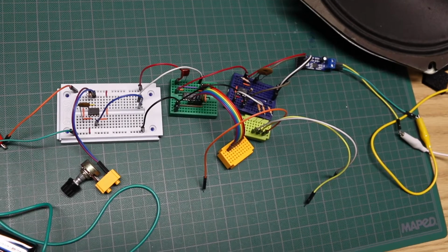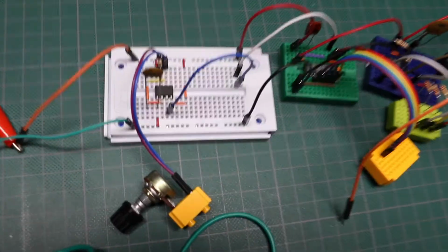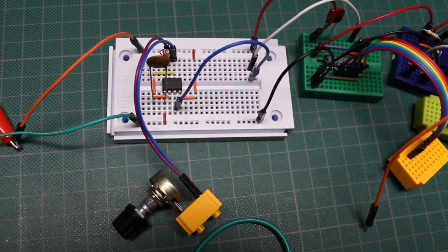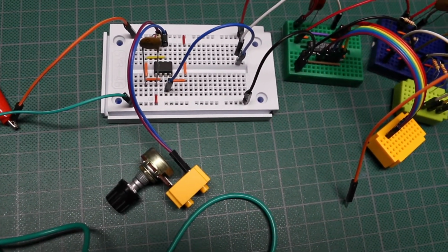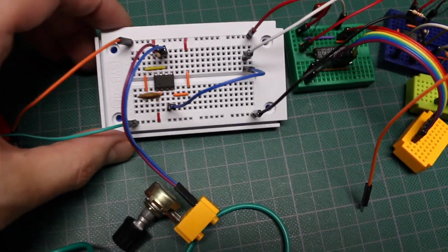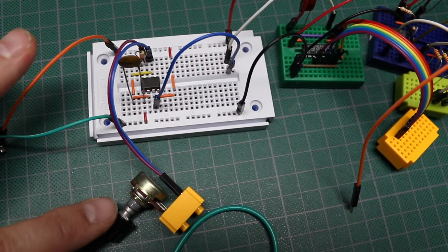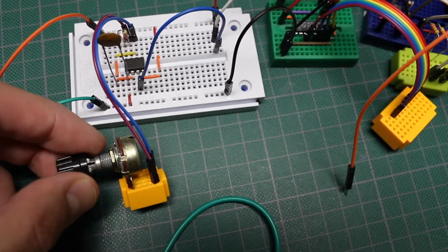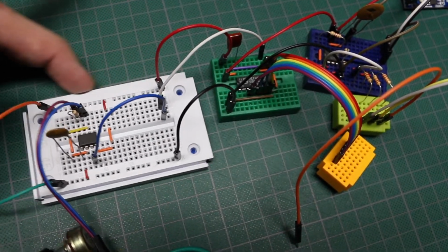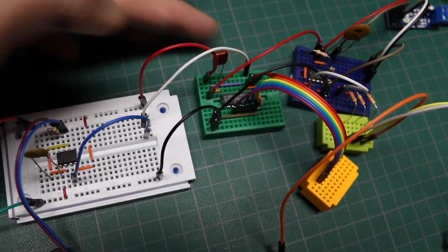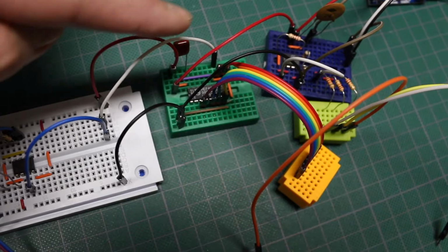So this is how the circuit ended up after several hours of messing around. I'm using a 9-volt battery, and the 556 chip actually turned out to be weird. It wasn't really working, so I actually found a 555 after all and put it on here on the white breadboard. So it's your standard circuit with the resistor, a potentiometer, and a capacitor. The potentiometer is mounted on the little breadboard, so the 9 volts comes into this board. I want it to use the power strips, and then I just pass it on. So this is the output of the 555. I bring it over to the edge of the board and then jumper it on to the next board.